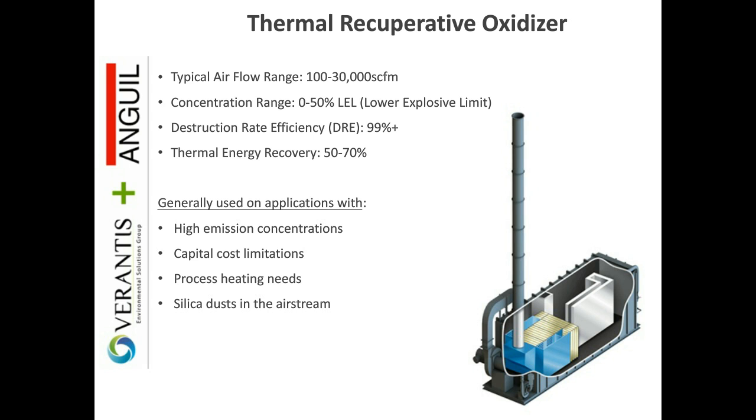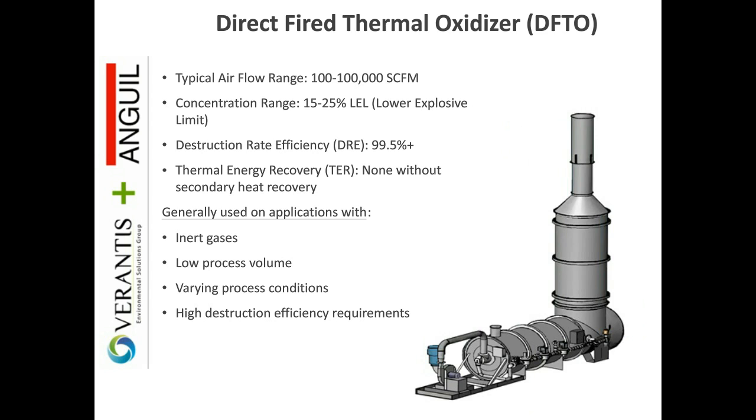Secondly, when I get to the concentrator system, you'll see that there's an oxidizer still tied to the concentrator system. It's pretty common to see a thermal recuperative unit in conjunction with a concentrator system, mainly because we are concentrating the airstream, so you tend to get into the higher percent LEL loadings. This slide, and then again on the next slide, which will be that vapor combustor.